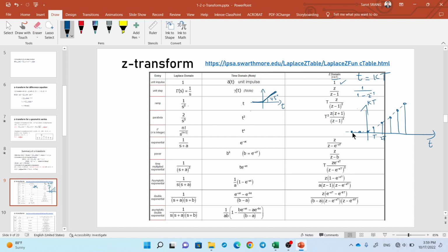In continuous time you have it like this. It means for continuous time you can pick any value of t, right? This t can be any value, you pick it and then you can compute the function. But for discrete you can pick k, you cannot pick t. Capital T is selected already, and then you pick the value of k. I mean, you want the sample at this time, and at this time, and so on.